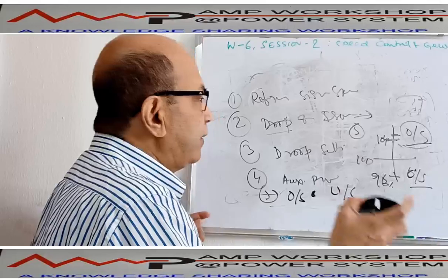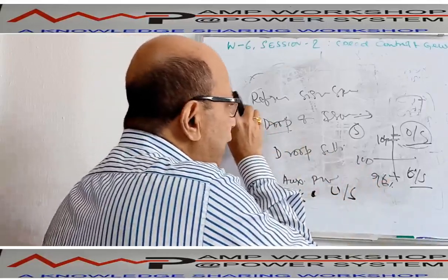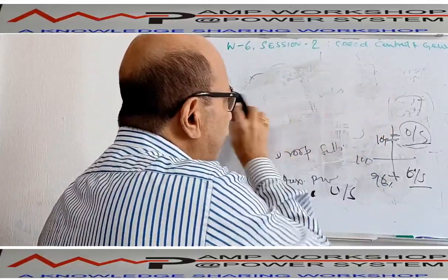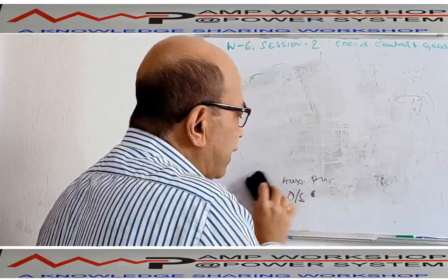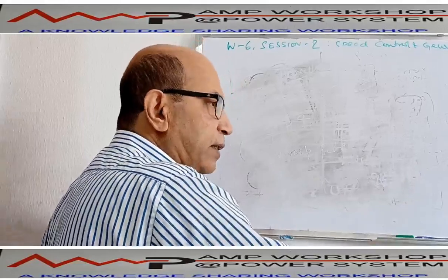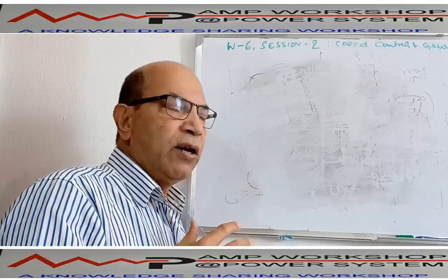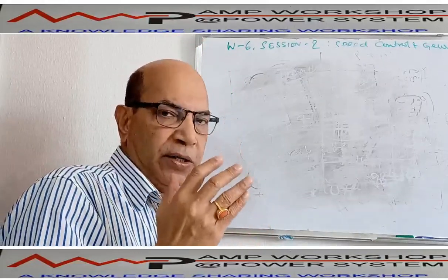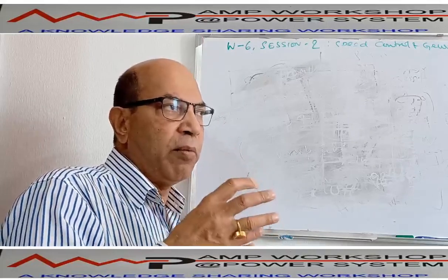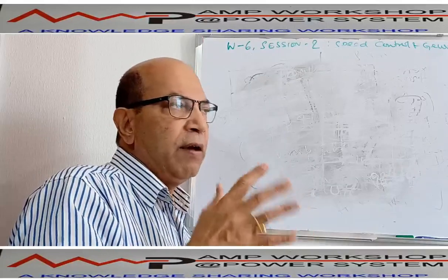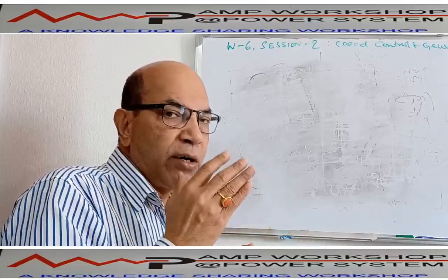Then the governor has another setting. The governor nowadays is a digital governor. It has another setting we call the stability setting or gain setting. What is that gain setting? Due to this setting, the governor may be very fast in operation, or it may be unstable. Suppose the machine is vibrating because the governor is giving fuel in such a way that the machine is not very stable.